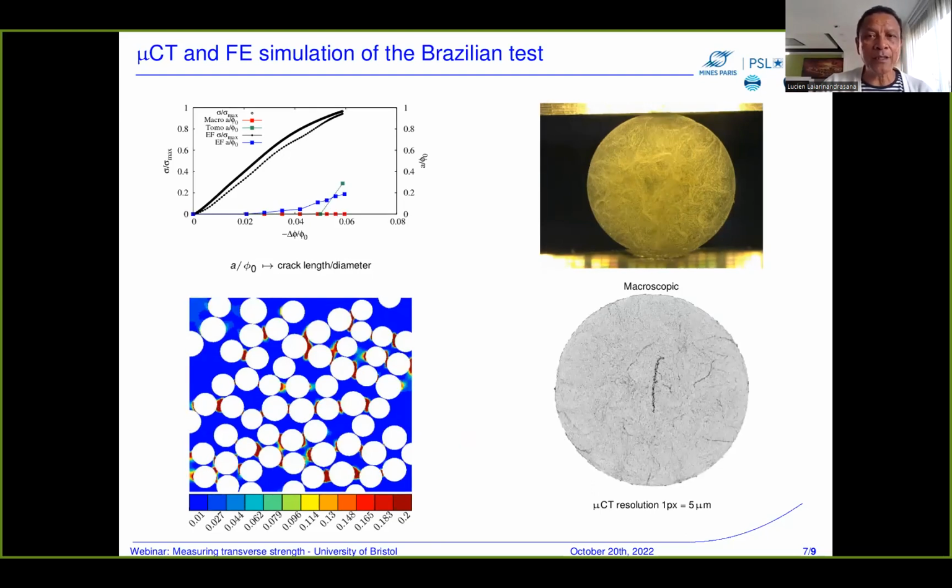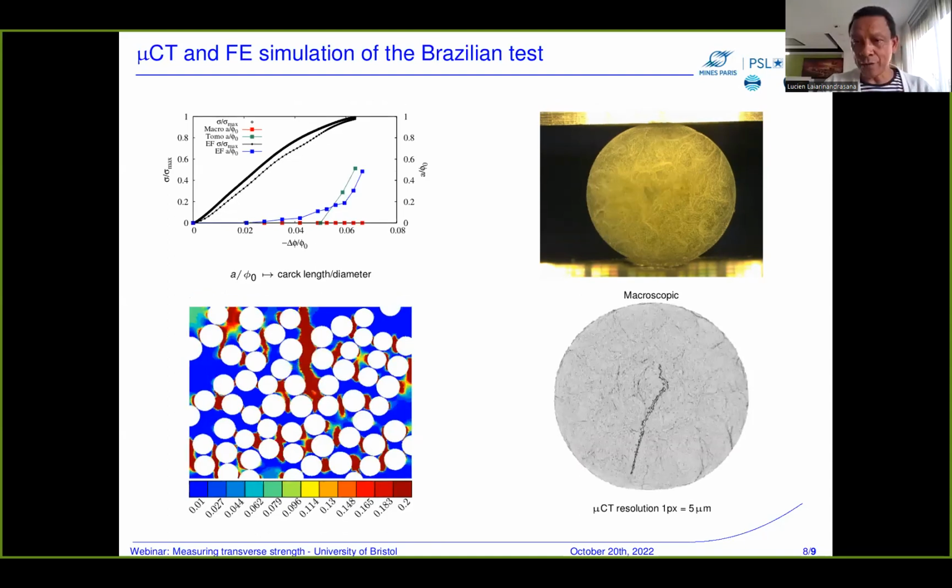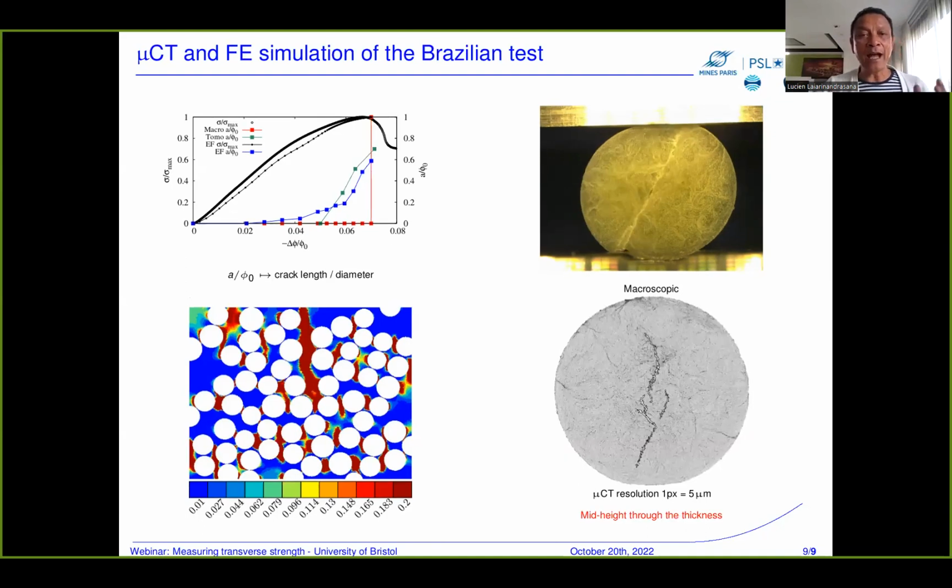So as you are doing this test in CT cells, you can see that as soon as you reach the maximum stress, there is a crack inside the material, visible here at the bottom right, that you can't see at the surface. The finite element modeling also shows a crack parallel to the direction of the compression that appears here. By doing all of this in situ testing with 3D imaging and running this finite element method, you can have this result.